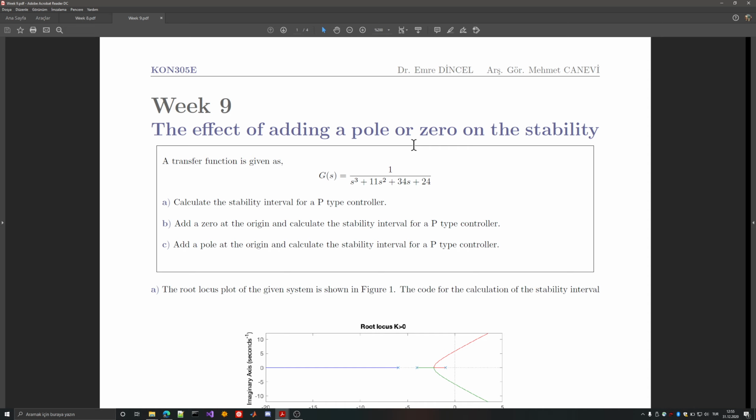It can be on the left side or the right side, or it can be at the origin, and it adds exactly at the origin a pole. So adding a pole at the origin will basically narrow down your solutions. But since you're then adding a variable zero, what happens is basically you're trying to choose a certain point so that you have a better design opportunity.